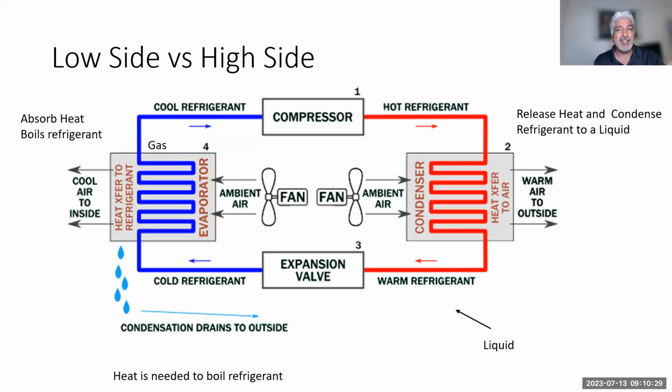Now, when I taught AC over 20 years ago and when I teach AC now, there are a lot of new tools out there. For example, your infrared temperature probe, where you can have a screen where you can see what's going on. Depending on what access you have to the condensers, those are a very valuable tool, because in the past, and it can still happen, we can get an evaporator that's partially clogged.